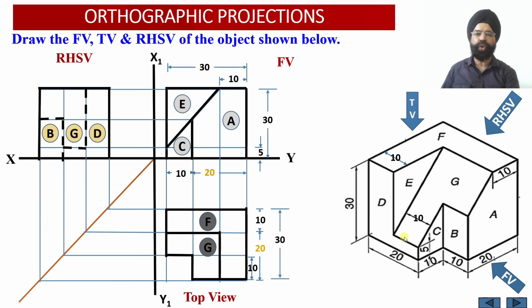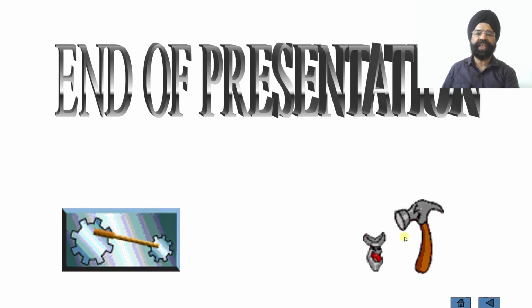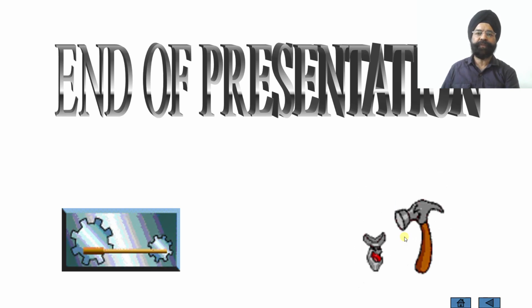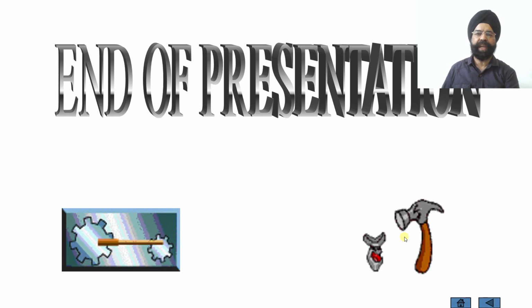Now we are going to remove the markings that we had made onto the orthographic projections, and now we are able to obtain a better correlation between the orthographic projections which have been obtained and the isometric projection. And finally, the redundant dimensions also we have removed so that we can get the final orthographic projections of this particular solid. So this is all for today. I hope that through this discussion you would have got a better idea about how to develop the orthographic projections of the solid when the isometric projection of the solid is available with us.